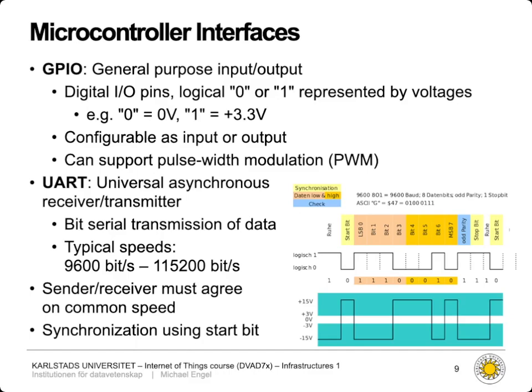A UART transmission has to synchronize the sender and receiver because both parties are only connected using a receive line and a transmit line. Essentially, you don't have any synchronizing information like a clock that tells both parties when a bit starts and when a bit ends. That's why it's called asynchronous.